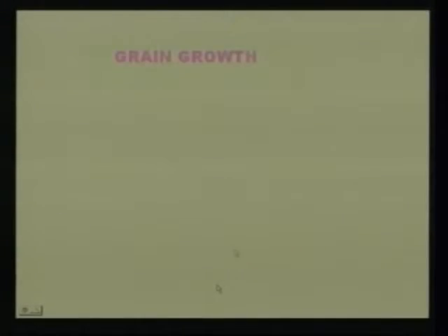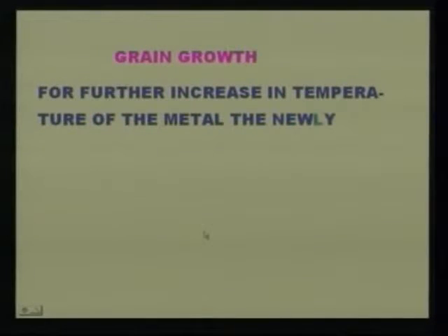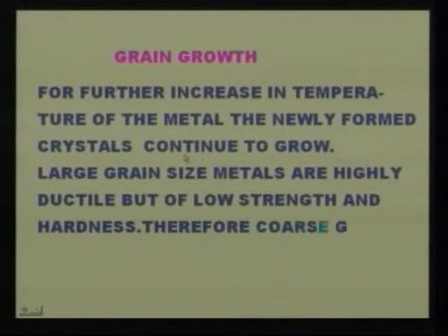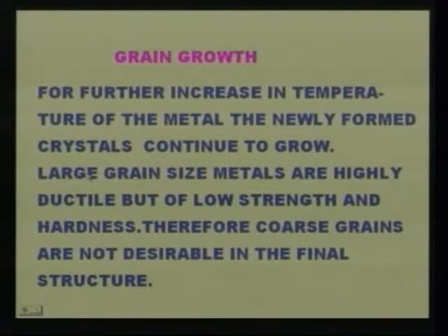Now, let us see grain growth. With further increase in the temperature of the metal, the newly formed crystals continue to grow. Large grain size metals are highly ductile but of low strength and hardness. Therefore, coarse grains are not desirable in the final structure.